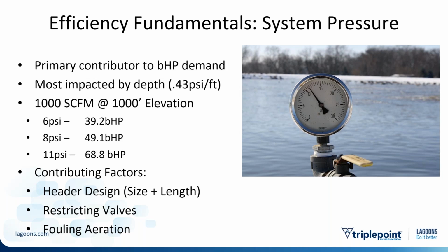And there are other contributing factors other than depth as well. You've got header design, how big it is, how long it is, how many restrictions we have along the way, and anything else that might be creating restriction like a fouling aeration system. We'll show you the impact of this later as well.